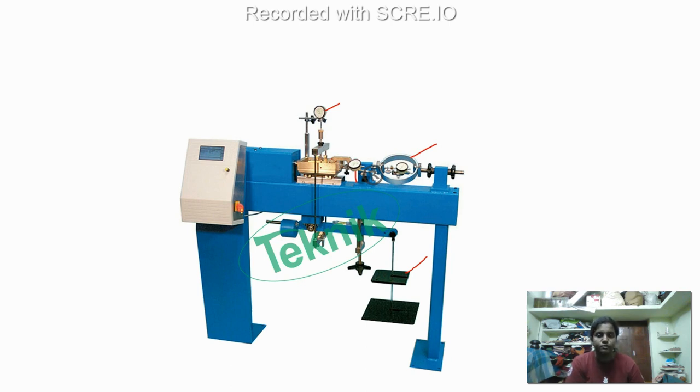During the failure, you will have a vertical displacement also, your soil will also compress a little. So you will be measuring this vertical displacement. So three things: vertical displacement and horizontal displacement. Your box is moving, you have to know how much it has moved. And this is your proving ring, and this is your normal load. These four things are what matter in this test.